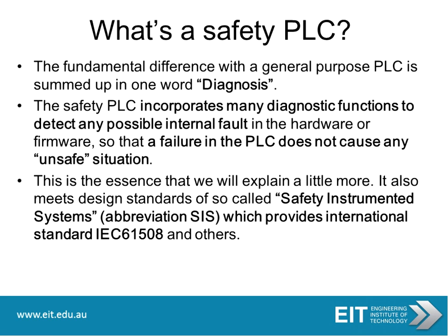So what is a safety PLC? The fundamental difference with a general purpose PLC is summed up in one word: diagnostics, as we showed you in all the slides up to now. Your safety PLC incorporates many diagnostic functions to detect any possible internal fault in the hardware or firmware, so that if you have a failure in the PLC, it does not cause any unsafe situation.